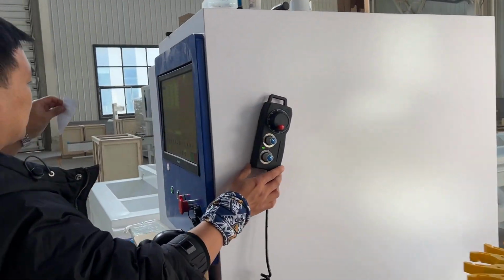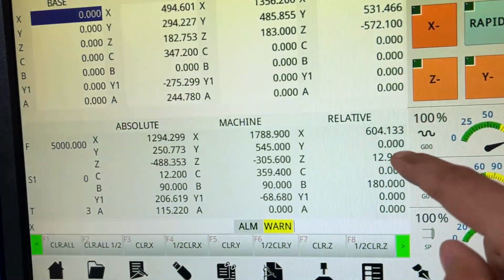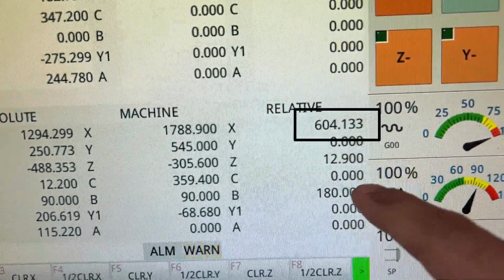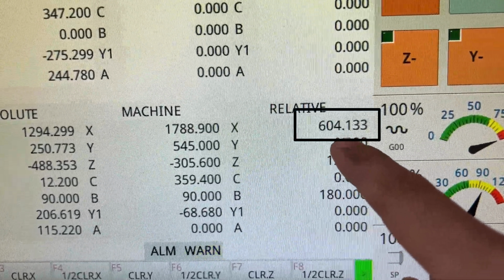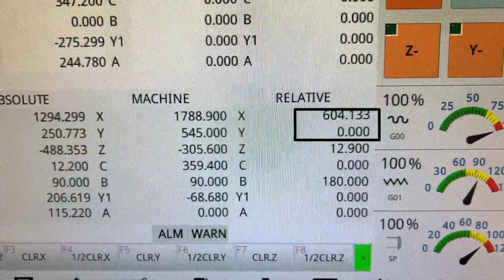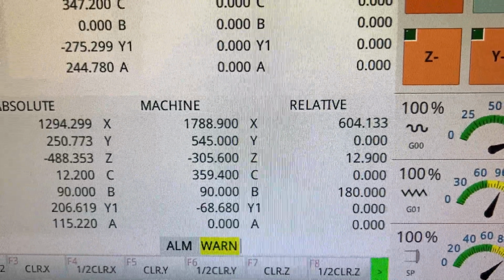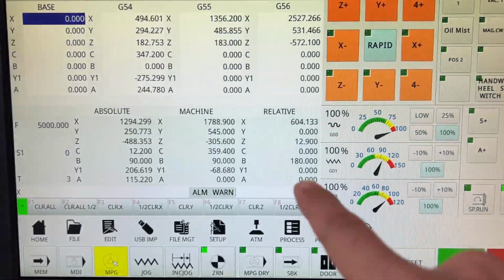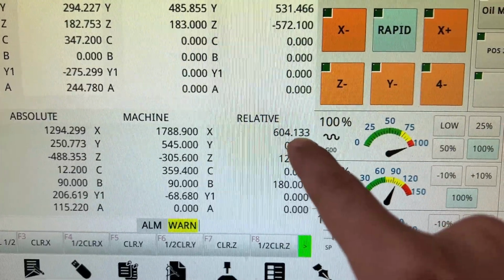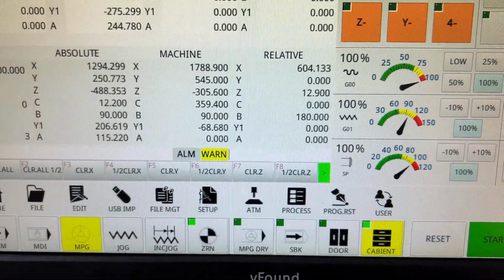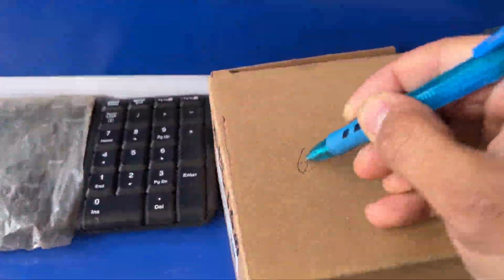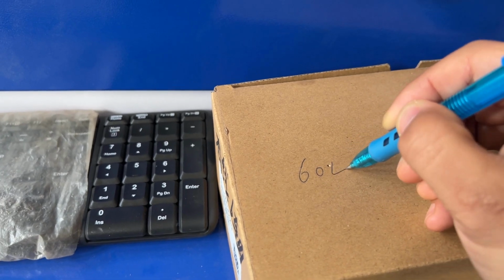After confirming the distance, come to the computer. You will find the x-axis coordinate. This is the distance the x-axis moves when the main axis angle is between 90 and -90 degrees. Record this number. Subtract the width of the square ruler from the distance moved along the x-axis.